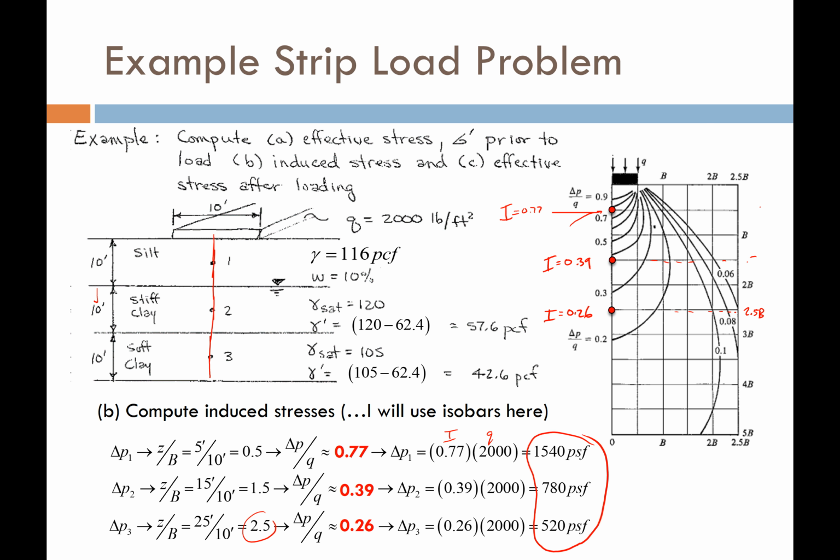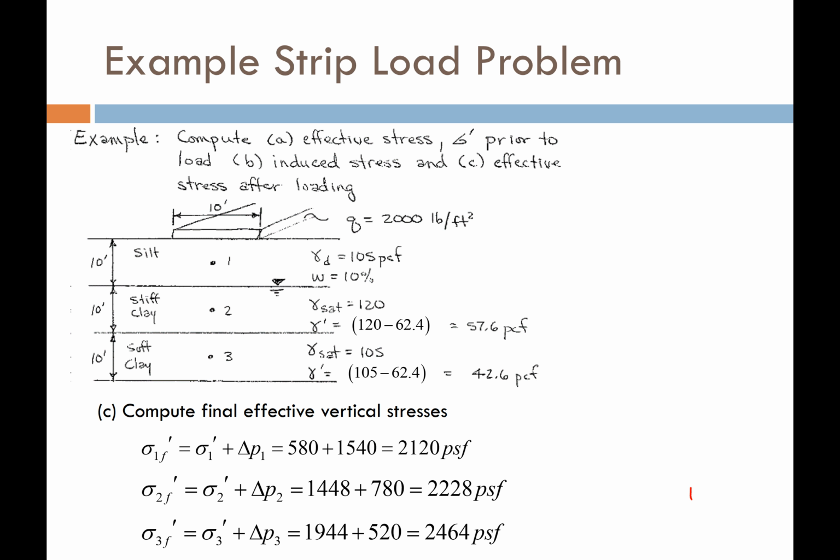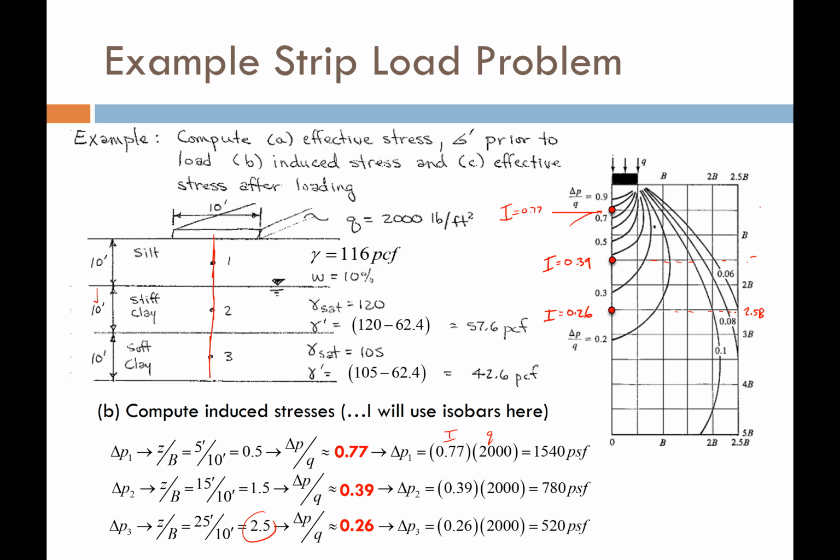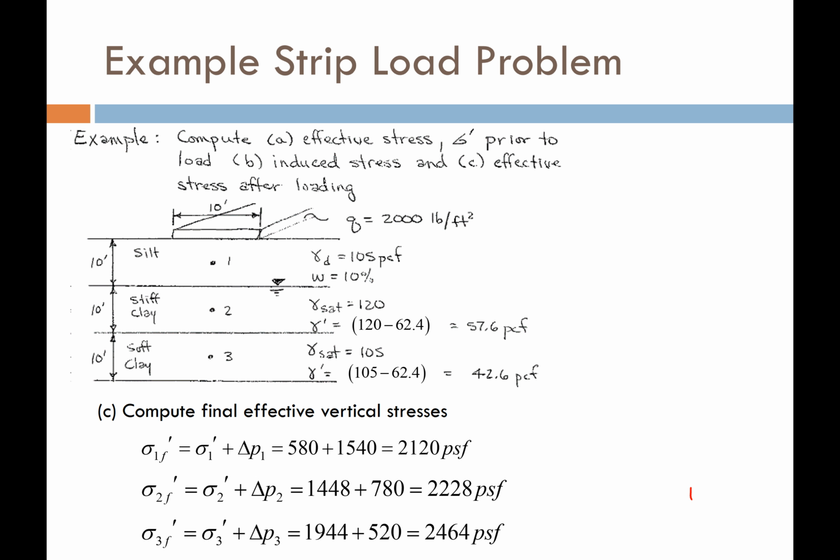Now I want to pause and let's review what these points mean. Again, these are the additional stresses that the soil is feeling due to my placing a strip footing on the soil. These do not represent the stresses that the soil was feeling before the strip footing was placed. Those we computed in the previous step.